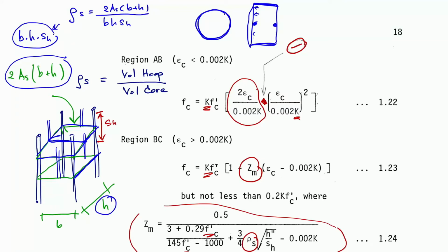That's why the longitudinal steel might also be placed at this point, and then you have something to help confine, so it will go like this, which is more difficult than going out this way.